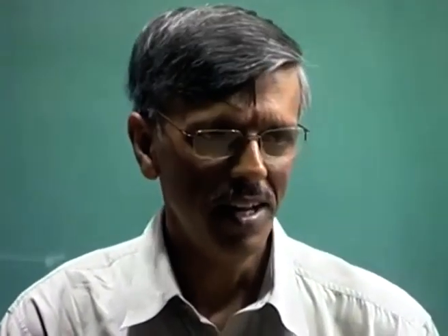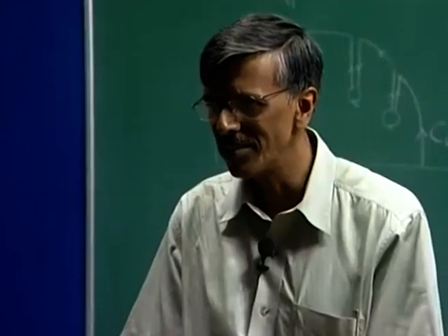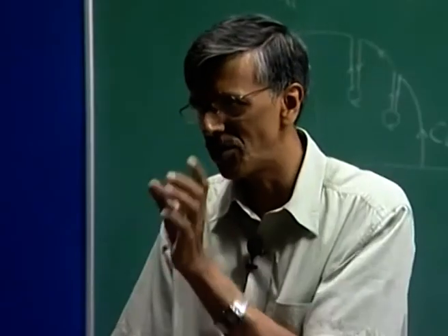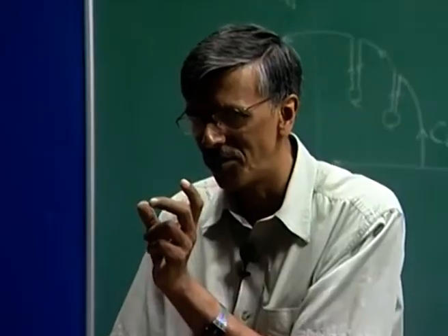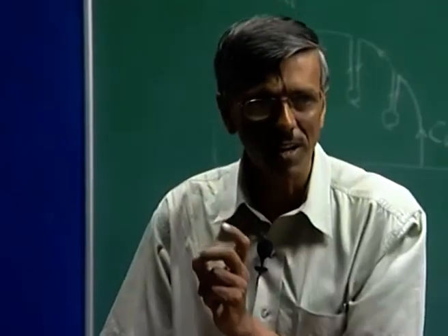I have a uniform flow. I am creating an excitation. What is the consequence? I am creating a stress field that strains the fluid, and the strain rate is proportional to what? The curvature of the streamlines. And if I create very large wave number, I am creating waves which actually distort very rapidly in small region, and alpha going to infinity, the strain rates are going to go to infinite value.